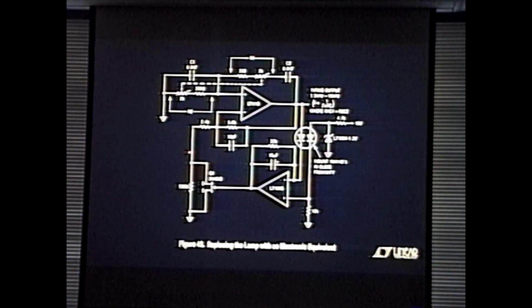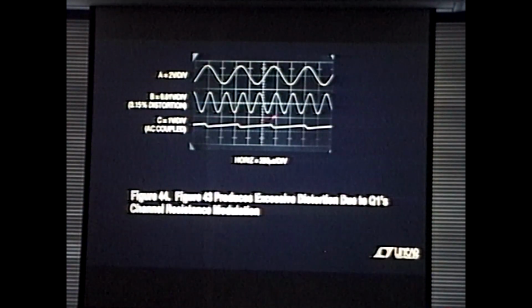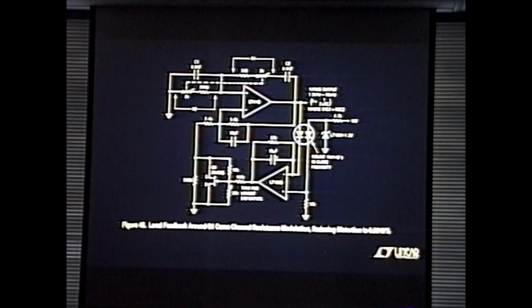Well, this point right here is moving in frequency. So the gate to channel voltage is not only set by the DC output of this, it's also set by the instantaneous value of this voltage. The differential between the channel and the gate is a function of this DC level, which we intend, and this point here, which is moving at frequency. Hence, horrible levels of distortion, 2F again, roaring out of this thing. You're 50 times worse. What's the fix?